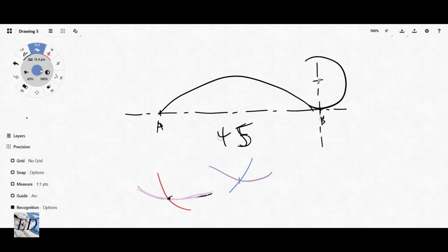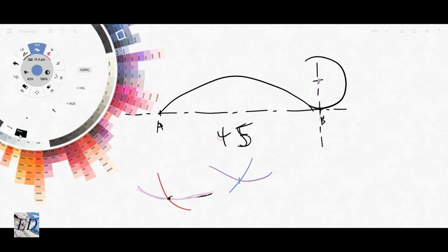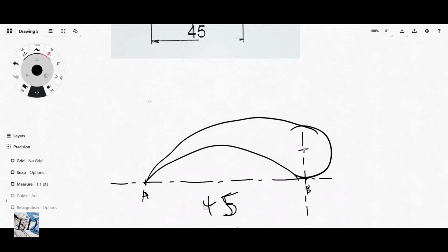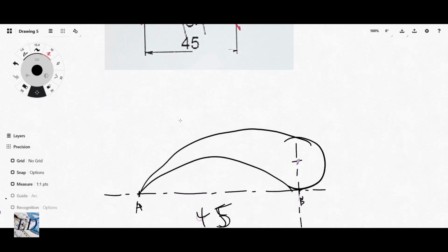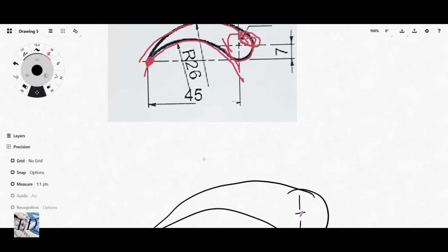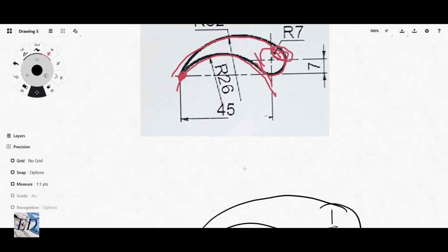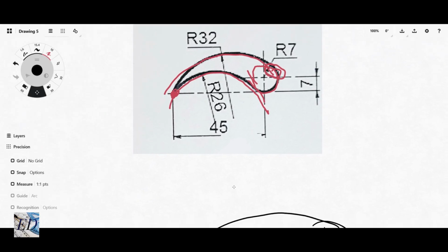Or if you took the right approach. So you open up to a radius of 32 and you draw your arc. That should give you the figure. This is not that complicated, but it requires you to understand exactly what you are doing, and the principles of tangency that you are using.